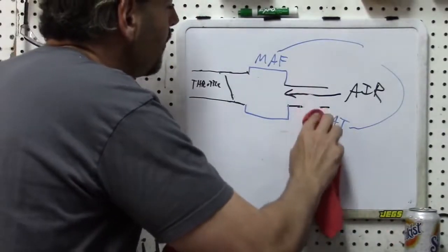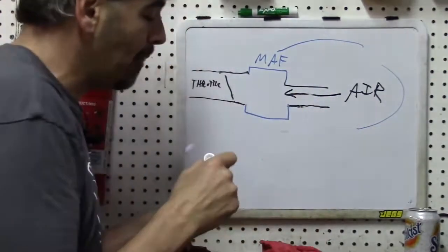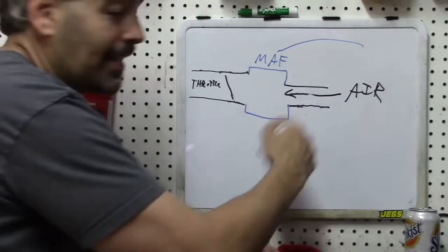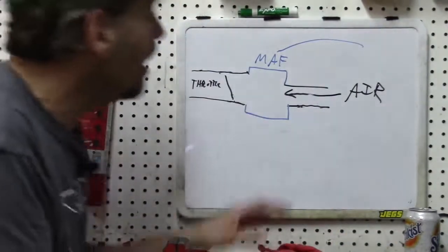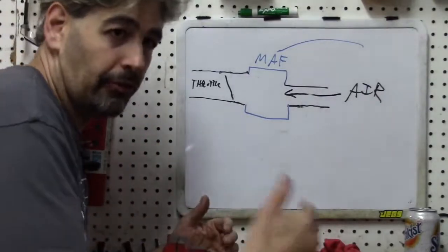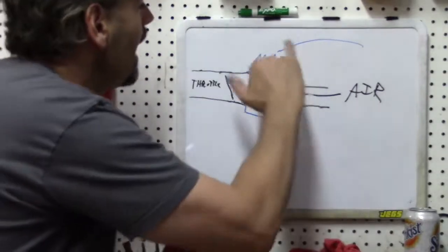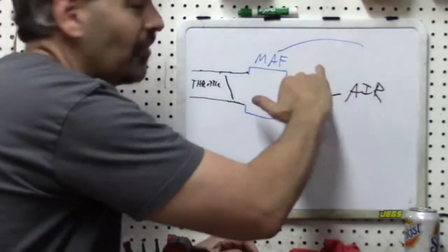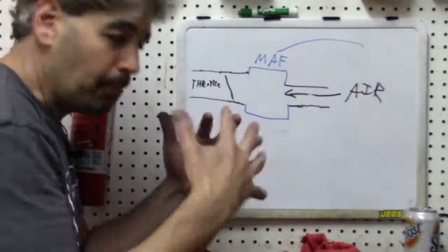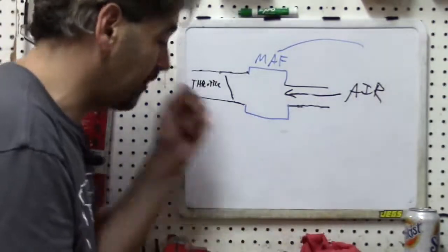Now, it goes without saying, if the intake air temperature sensor is inaccurate, the readings from your MAF will be inaccurate. Not that the MAF itself is inaccurate, but the extrapolation of that calculation for weight over time would be inaccurate. So again, another example of what I call the potential for a referenced code, where if the IAT is grossly misestimating temperature, then the MAF sensor could get blamed by the PCM when it determines the air-fuel mixture is wrong. So very important to put everything together, as you see. Now let's go ahead and talk about the different types of MAF sensors.